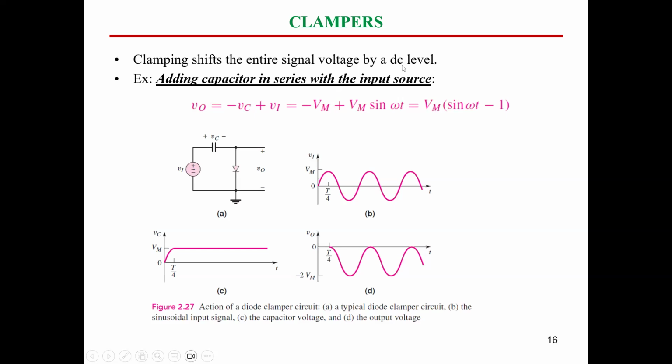For instance, here, the output volt we have in this circuit equals, if you apply Kirchhoff's voltage law here in this loop, let me write this here. If you apply Kirchhoff's voltage law from this terminal to that terminal, you will find that Vout equals, moving in this direction, you will see the minus sign firstly, so minus VC, then plus the input supply, so plus the input.